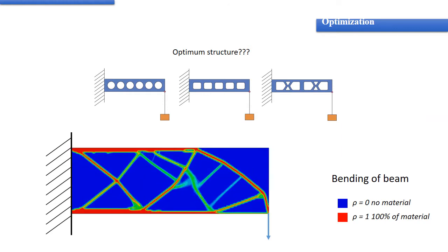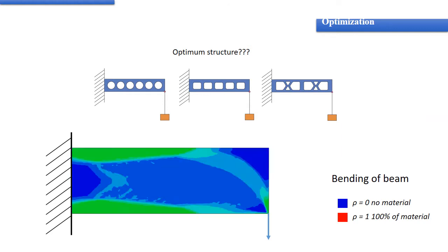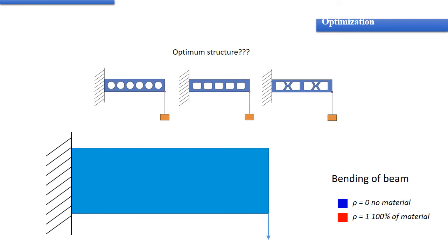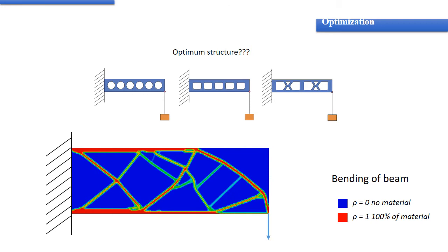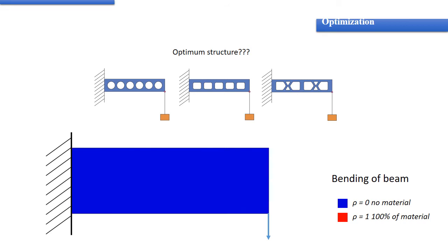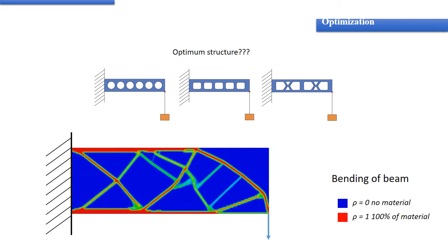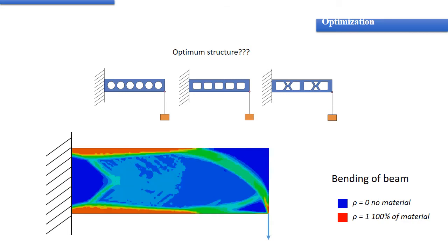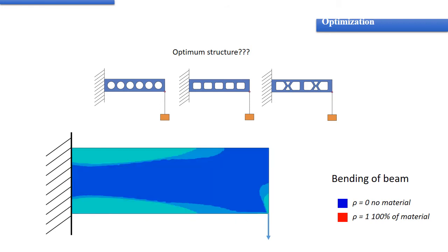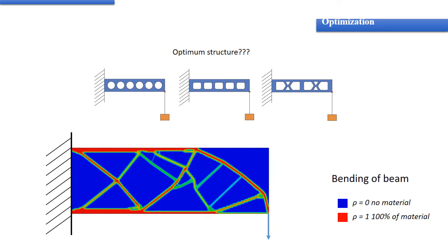So the question is, we now have such interesting tools for designing structures, optimization, which we usually call topology optimization. If we need to choose a structure for some kind of criteria, this algorithm helps us to redistribute our material in the most optimal way. Here, blue color means we don't have material, and red color means 100% of material. 100% of material means 100% of stiffness.